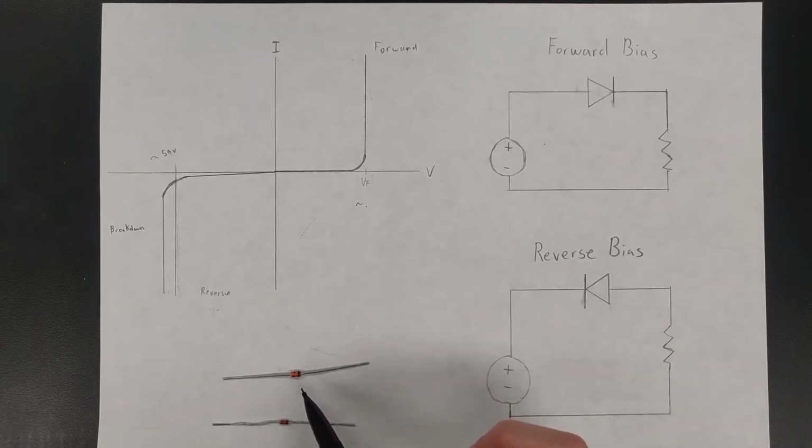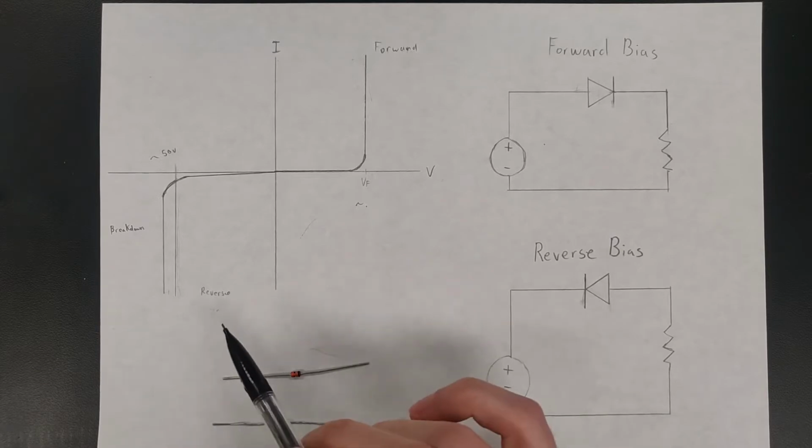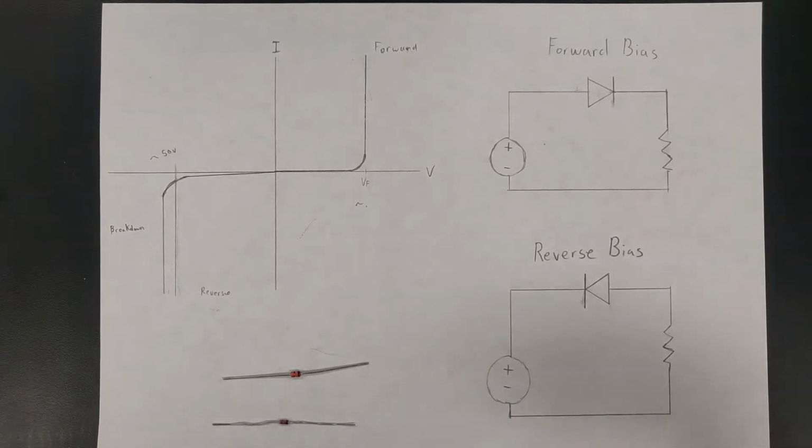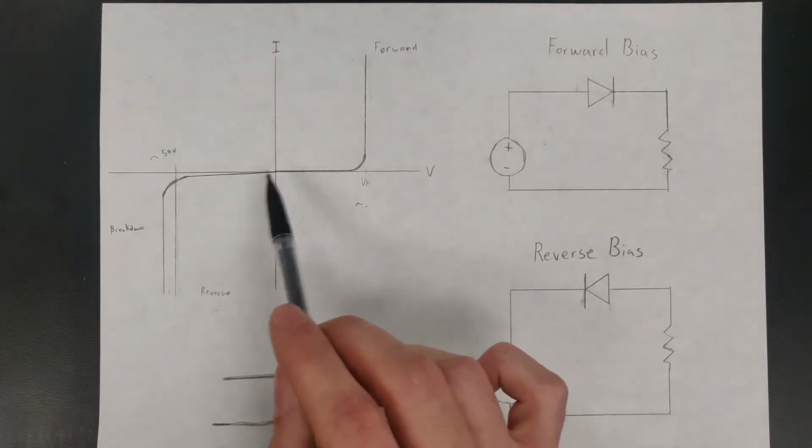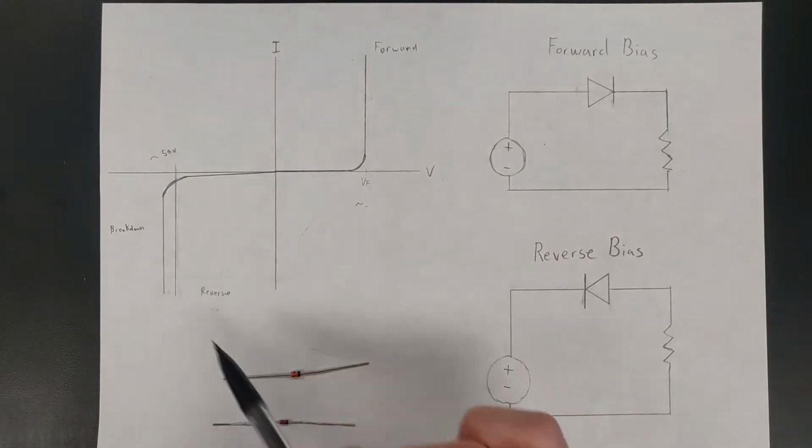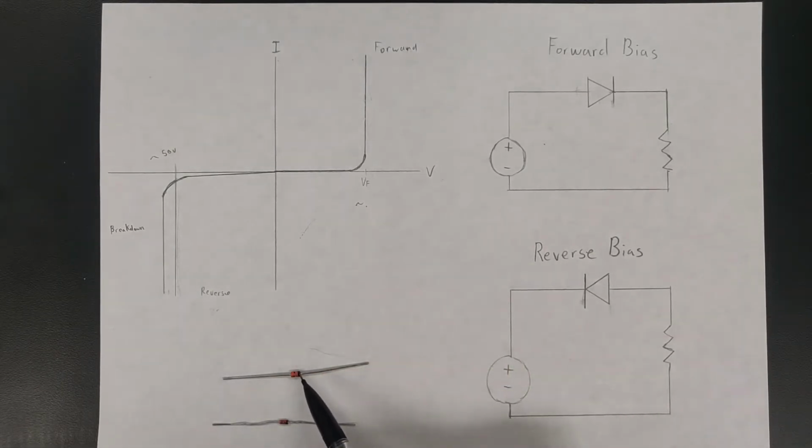This component is constructed in such a way that it's intended to break down and is a reversible process, and we're going to be using it in later experiments. In this lab, we're just going to be creating a characteristic voltage versus current plot for the reverse bias orientation to see how it's different from an ordinary signal diode.